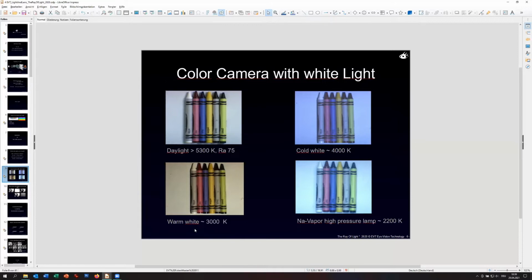And it's still valid based on surrounding influences like sunlight or whatever. Color is very sensitive. Our eye is always recalibrating, or our brain is always recalibrating the eyes based on the surroundings, so that we always see red as red. But the camera doesn't see red as red. So at the end, you need what is called white balancing, and you have to do it actively. The camera supports it, but you have to initiate it, and you don't know when.